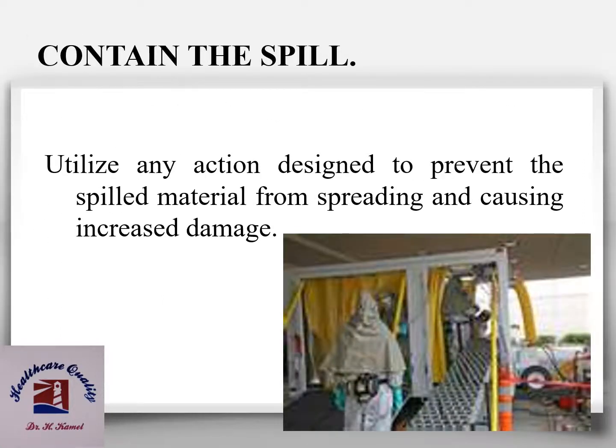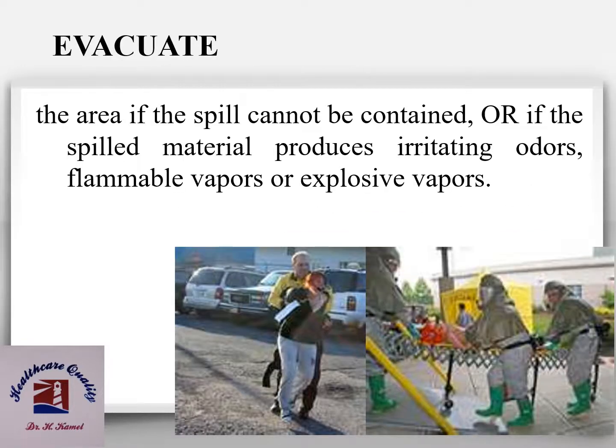Then, contain the spill. Utilize any action designed to prevent the spilled material from spreading and causing increased damage. Evacuate the area if the spill cannot be contained or if the spilled material produces irritant odors, flammable vapors or explosive vapors.